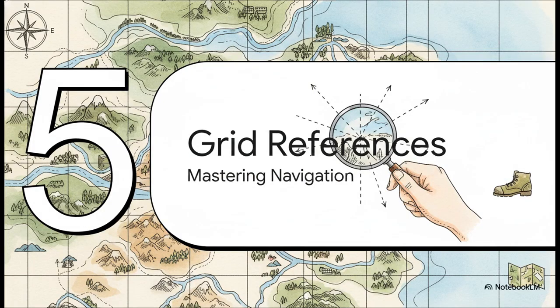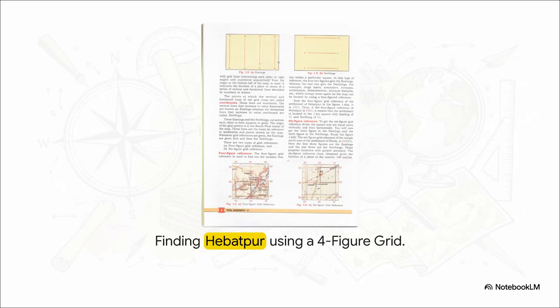And now for Section 5, Grid References, Mastering Navigation. With that coordinate grid firmly locked in our minds, we've actually reached the climax of our explainer today. It's time to take all this theory and turn it into a highly practical, real-world skill. We're going to start by finding a general location using what cartographers call a four-figure grid reference. Say our goal right now is to locate the settlement of Hipatpur. A four-figure grid reference will allow us to identify the exact 1 kilometer square where this settlement is located.